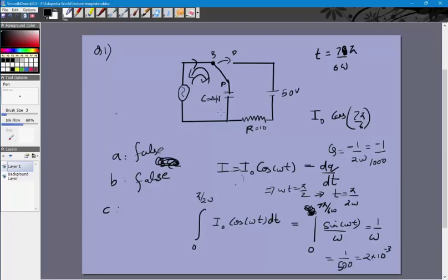So what is the potential difference across this? That will be equal to Q by C, which is 1 by 1000 if you just take the magnitude, divided by 20 into 10 to the power minus 6, which is equal to, this is 10 to the power 4, so 1 by 2 into 10 to the power minus 2, or 100 by 2, or 50 volts. Right, so the potential difference across this is 50 volts.